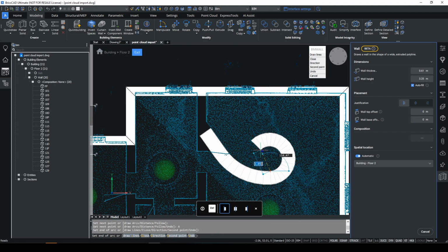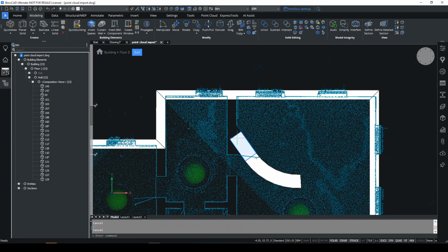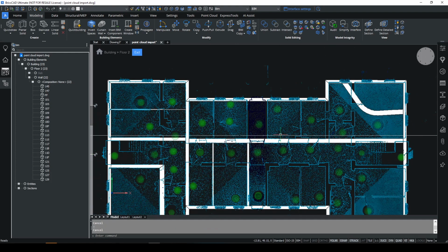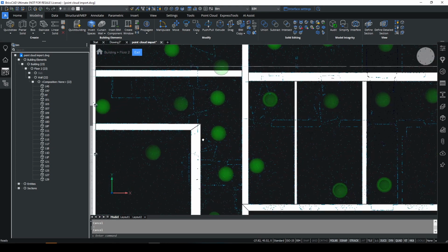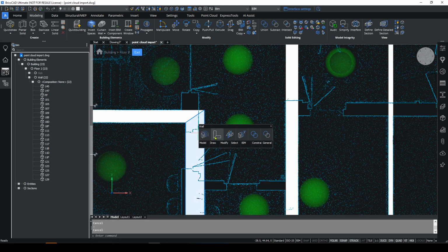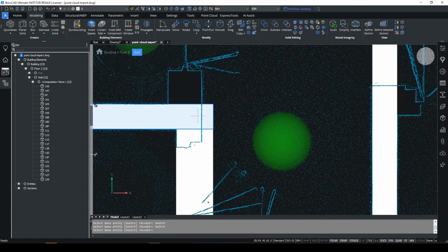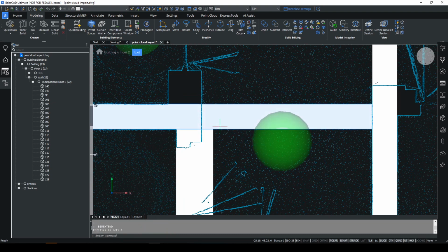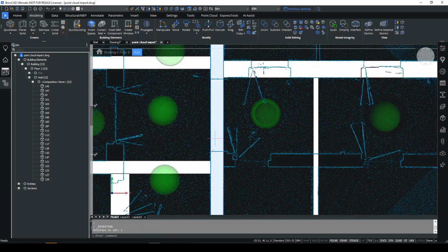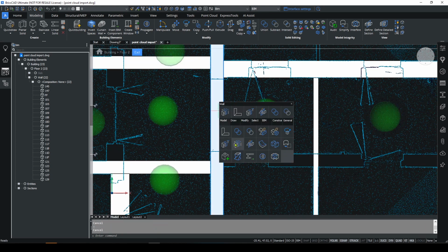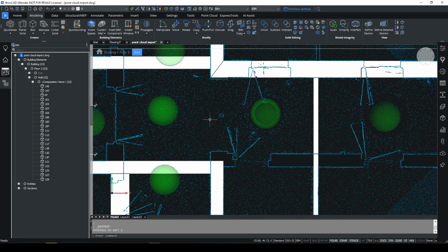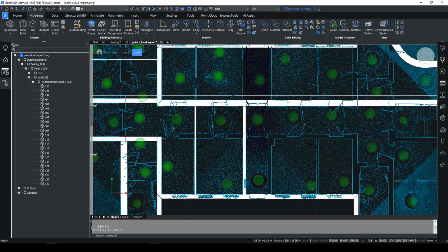Depending on what you're trying to capture, you run that, and the exact same command works for BIM extend to have these meet. Some of the other versions of what you can do here are run the BIM trim command. So let's change this to a version where we've got walls butting like this, and extend this along here. Now what we want to do is trim this wall where these two meet. So you hover over it, and instead of using BIM extend, use BIM trim, and that will cut these two walls here for us. You can see how quickly you can run through these.